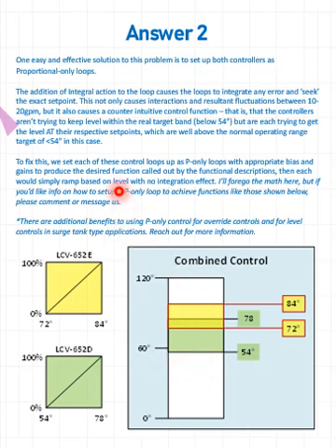And what you do is you avoid the interactions of these two control loops or control valves. You allow them to work together, both of them pushing the level downward by discharging overboard to balance that flow out for those conditions.